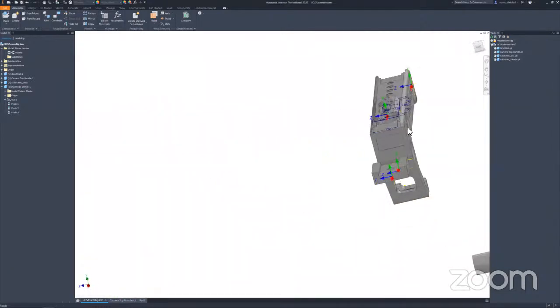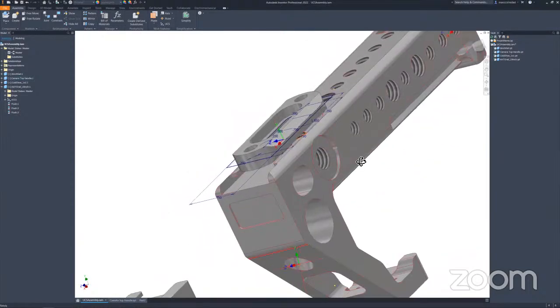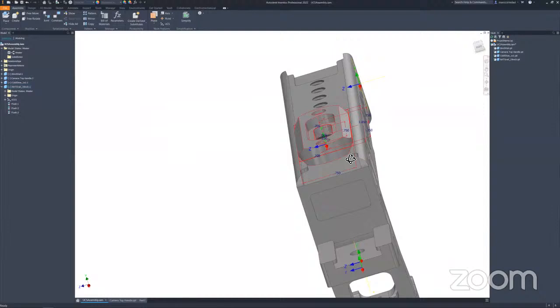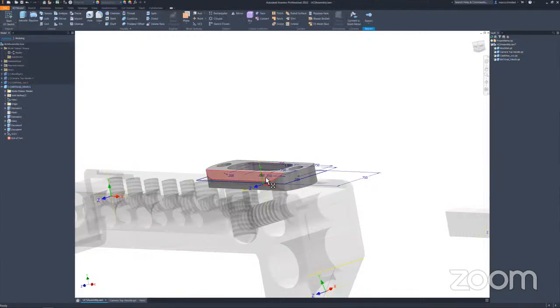And this is where direction matters. You could see that I didn't quite set it up the way I wanted it. I wanted it to be going across it and not going along this. So I can go back into here and then edit the Y, change it, rotate it 90 degrees.